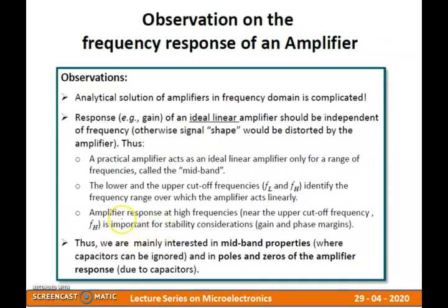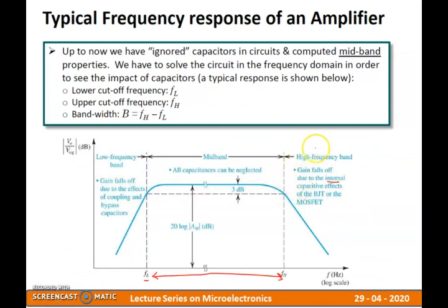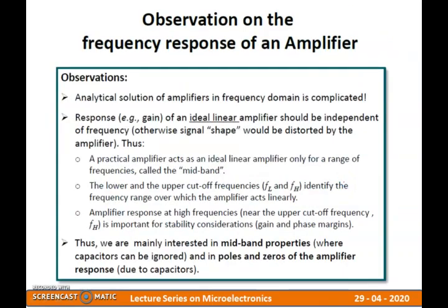Now here I have made a statement that in the high frequency band the gain is rolling off because of internal capacitive effects, and the gain is rolling down to 0. Now here I will make one more statement: the amplifier response at high frequencies, that is near the upper cutoff frequency, is very important for stability considerations. Again, I will throw more light on this particular statement in the subsequent slides.